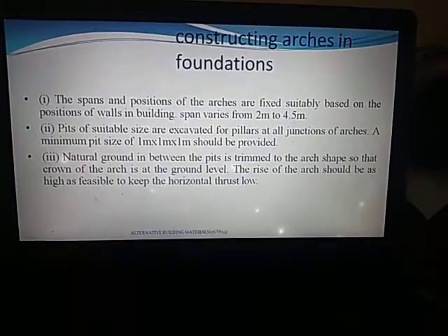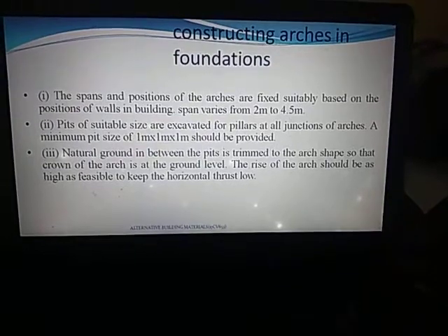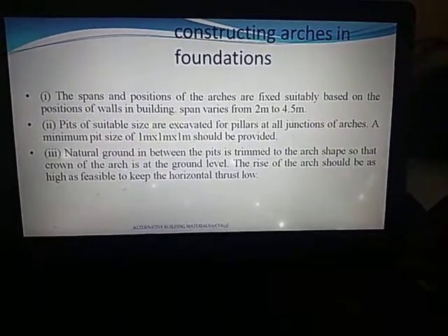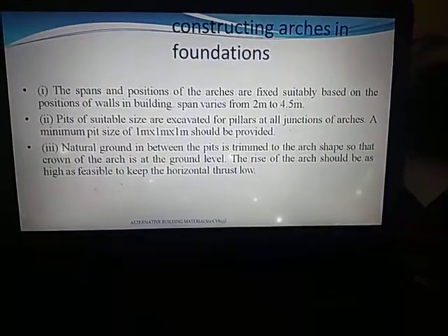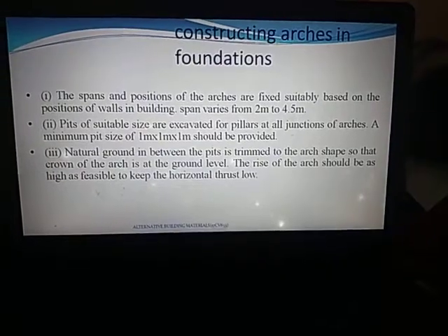Next step, you have to excavate the pit. Pits of suitable size are excavated for pillars at all junctions of arches where you are providing the arches. So near the junctions you have to provide the pillars. A minimum pit size of 1 meter by 1 meter by 1 meter should be adopted.